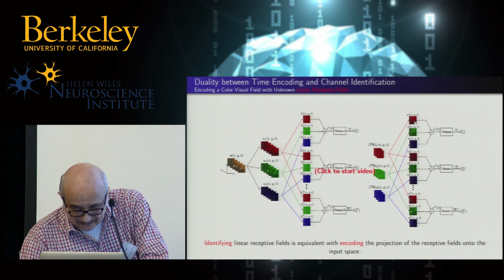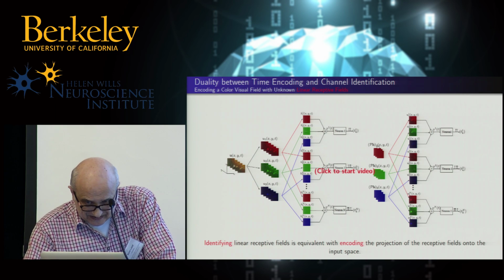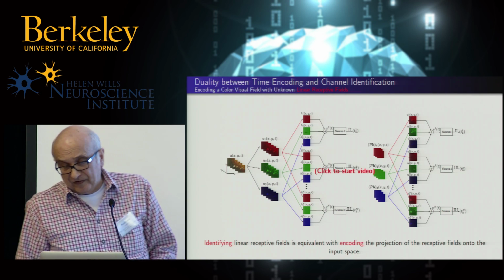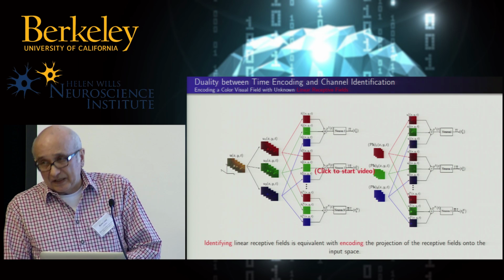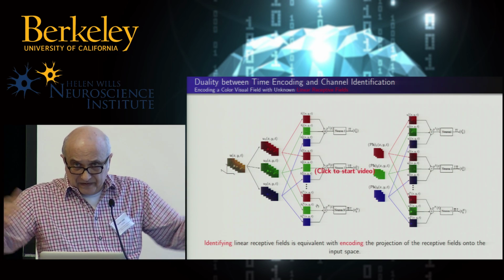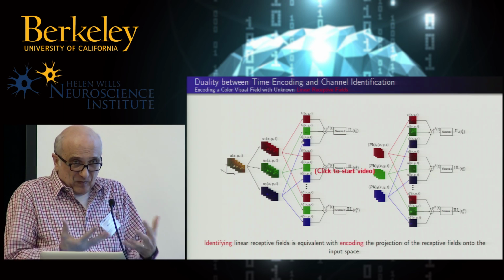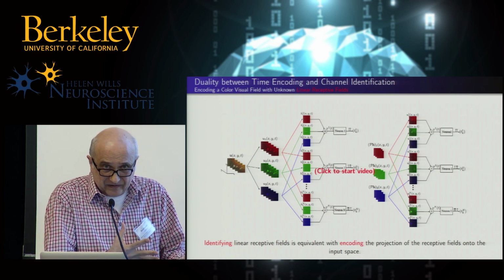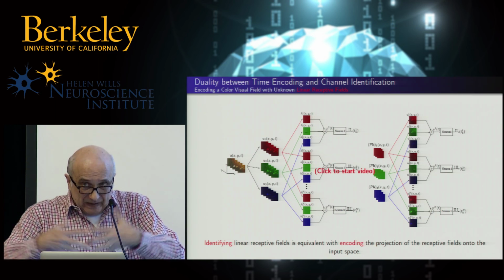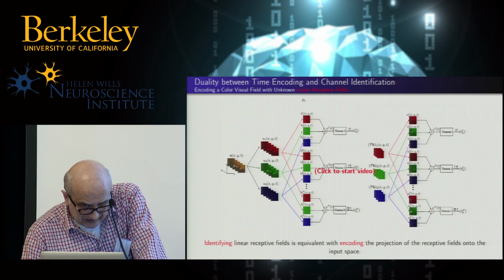So you see here, these are all used. They are controlled in the experiments. The H's, the filters, are not. Now there is also a P in front of those filters, and that means a projection. What does that mean? From a practical standpoint, if these filters have a larger bandwidth than the input signal, then of course you cannot find out the actual value of the filters because you're not driving them. So you have to drive a wide bandwidth. And people in practice often use white noise. White noise leads to problems. Here we have band-limited signals.